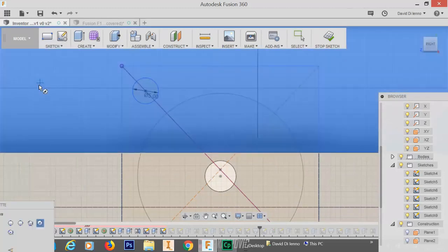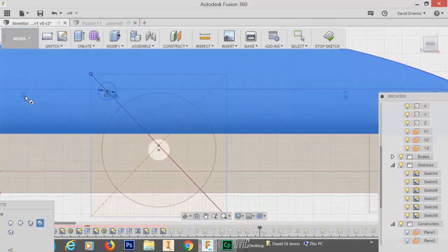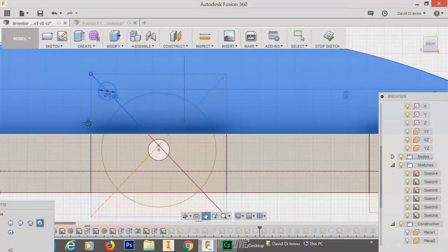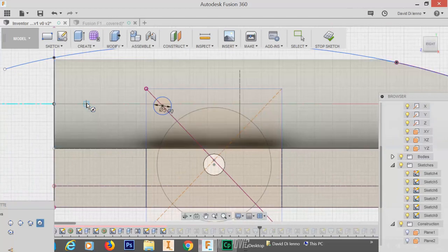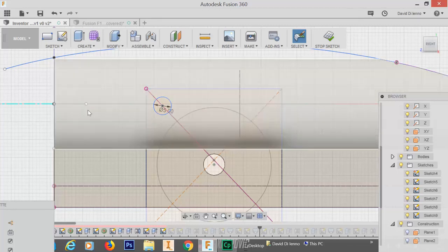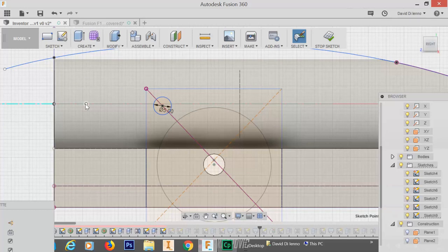Repeat center diameter circle and make it this bit smaller. Bring it across. Hit escape. So let's go for about here. Alright. And we'll make it 3 millimeters. Hopefully that pops up in a minute, because I thought I did do a 3 millimeters. Maybe I did a 0.03.